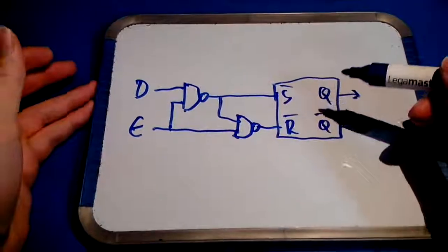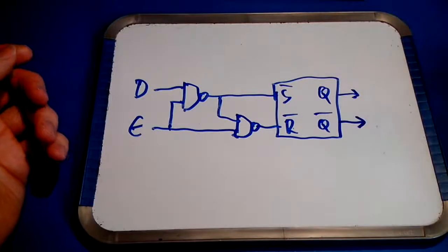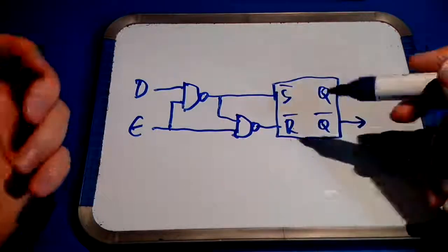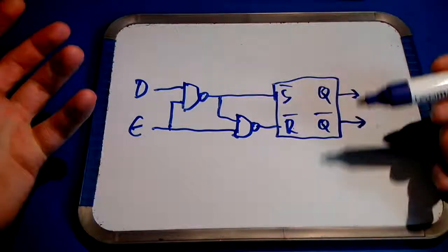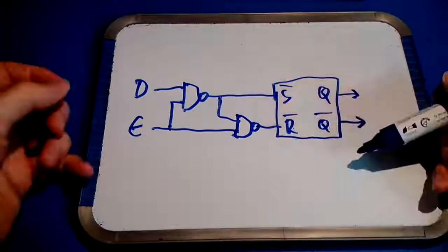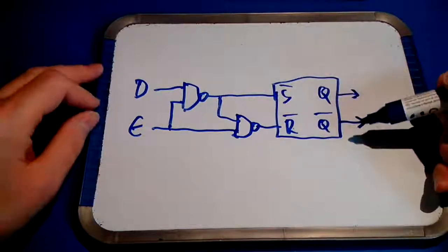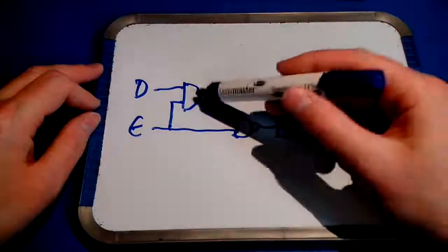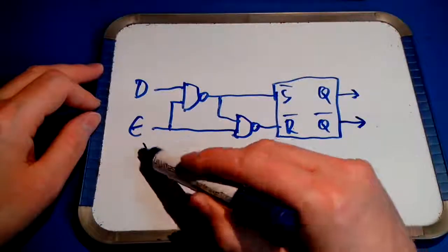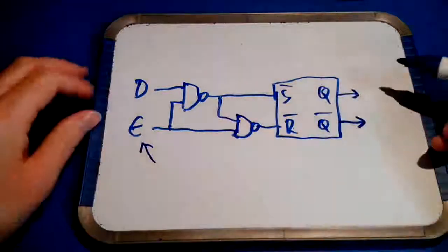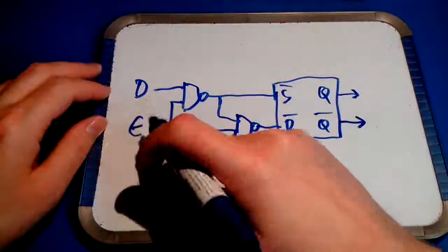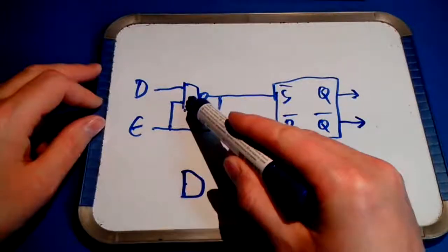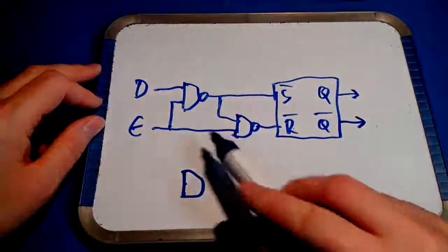Also, in the previous video talking about the 8-bit latch, we used a truth table. Now in retrospect that may not be very clear, it doesn't tell you much about how this block works. So let's do it another way now. To see how this works, because these two are NAND gates, let's first look at what happens if the enable input is 0. Remember that, as you can see, the enable input only serves as the input of both NAND gates.